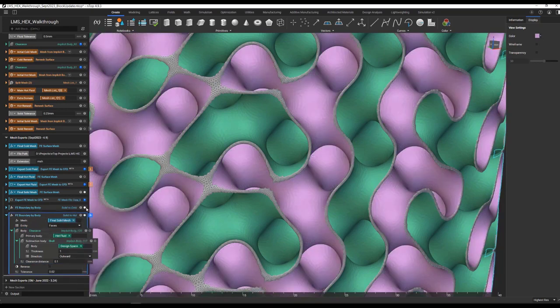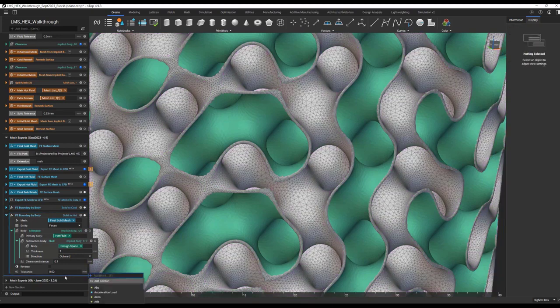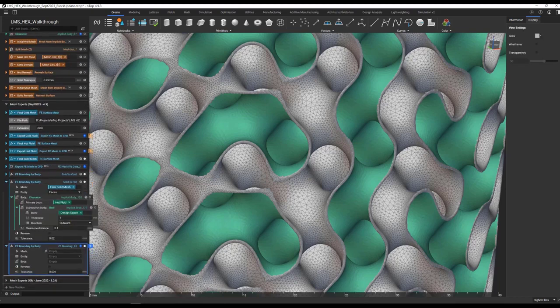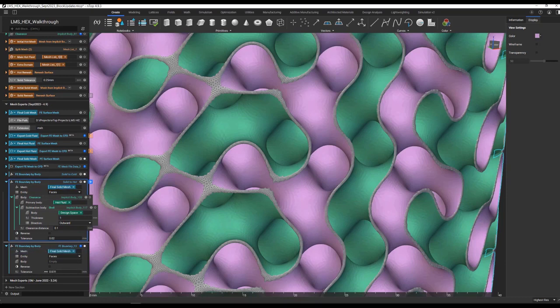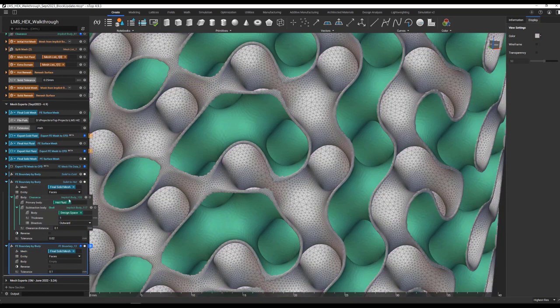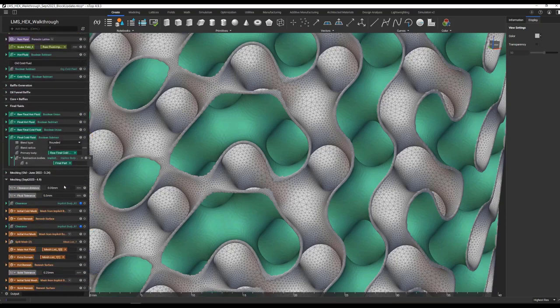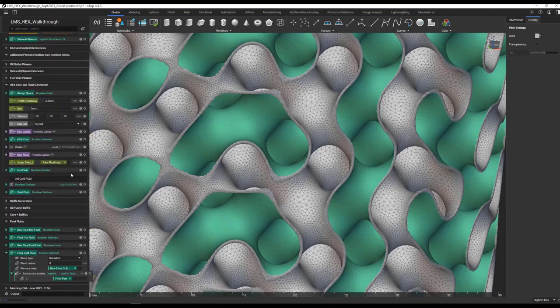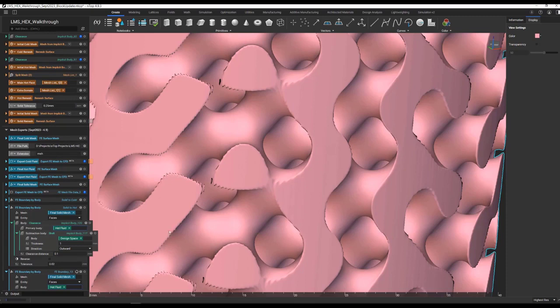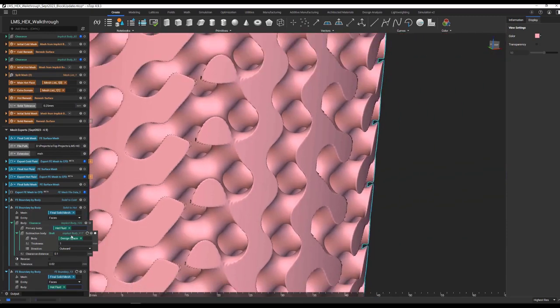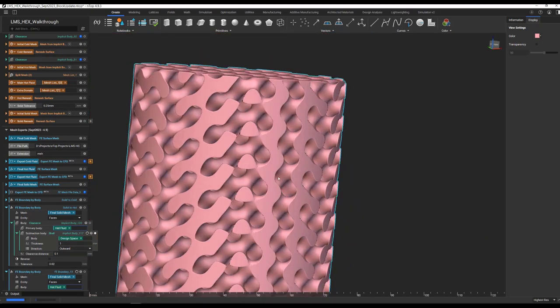If we, and I'll go ahead and do this now, we're going to hit S and add a new boundary by body block. We'll select faces, 0.1, hot fluid. So while this calculates, we'll talk about the clearance block. With this clearance block, I took the hot and cold fluids, these original ones that we created up top. I took a shell of my design space going outward, so when this finishes rendering, we'll see what that looks like.